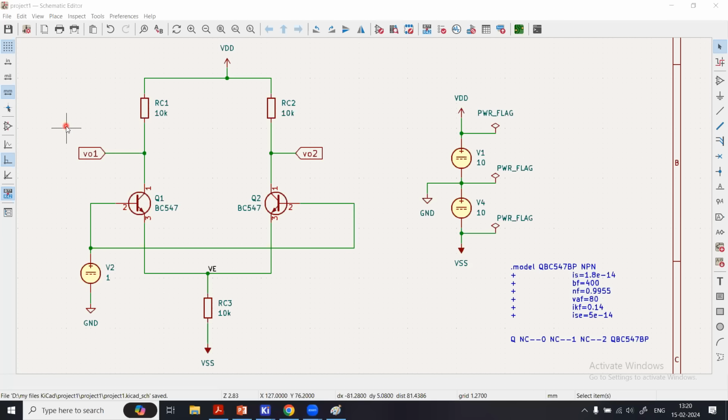So in this module, we are going to explain that after creating a schematic, the usual practice is that you perform simulations. You check the electrical rule check, whether you have taken the proper components and the devices have made their connections properly. In our previous modules, we explained how to perform the ERC, how to pick up the components from the library and devices, how to interconnect them, and after performing ERC without error or warning, we demonstrated how to perform the basic simulations.